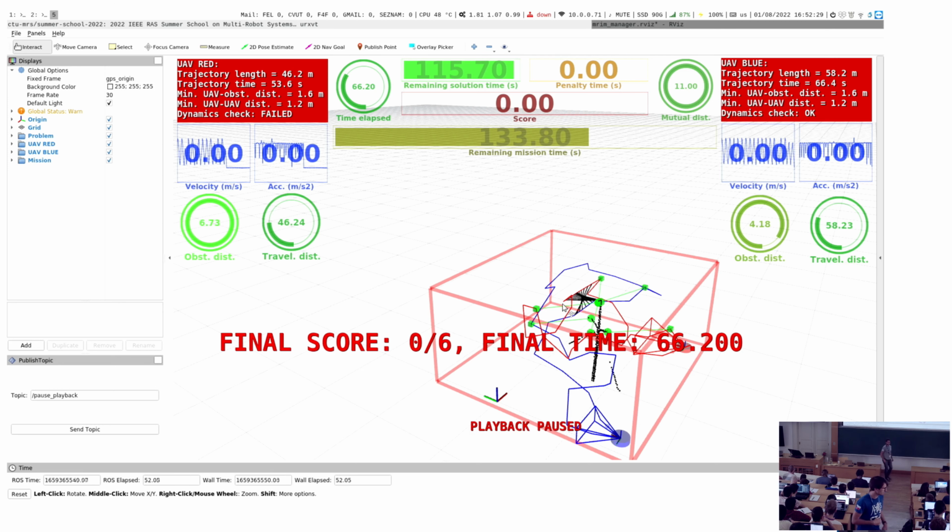Just one curiosity. Which kind of library in C++ do you use for the implementation of the MPC? So our MPC is written in CVXGen, which is a generator library, so-called. You give it a math description of the problem, and it spits out C code for the solver for that particular problem. CVXGen was developed by Stephen Boyd, I think. Is it? Yeah. And it's quite old for now. It only solves convex optimization, and it's not that fast, but it's reliable enough.